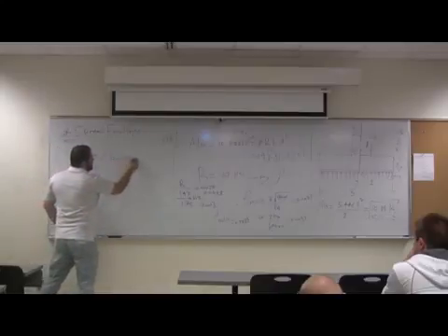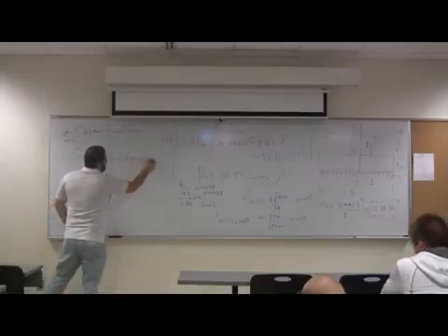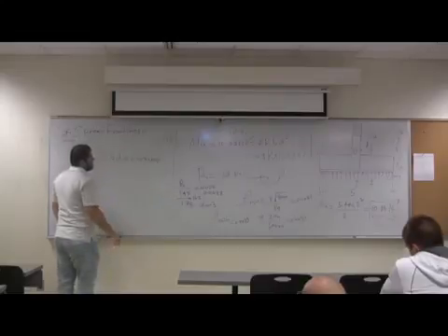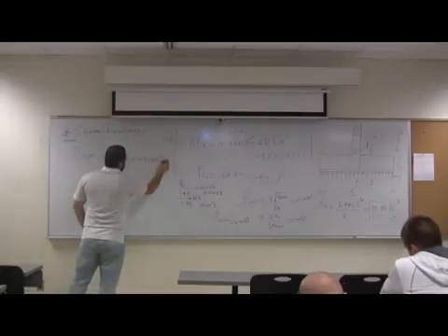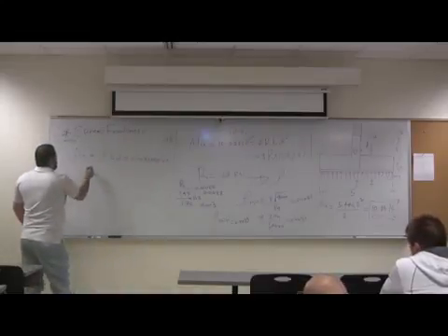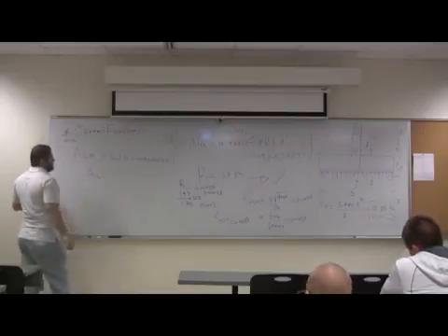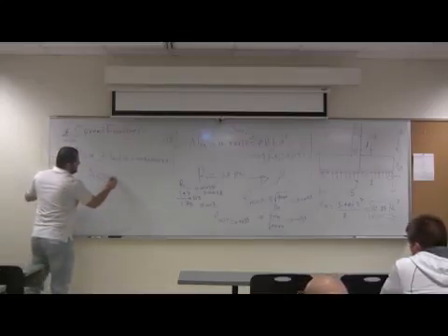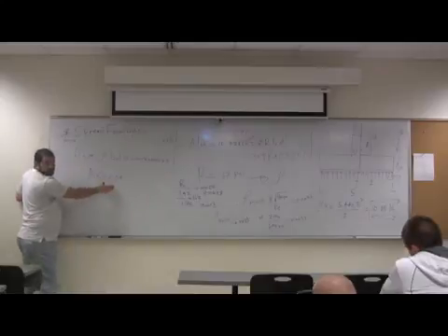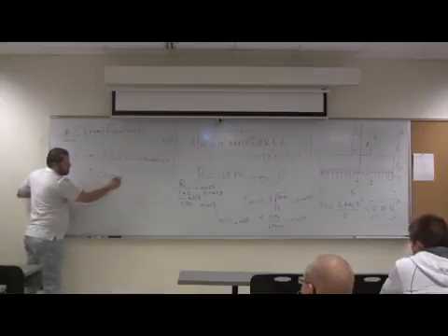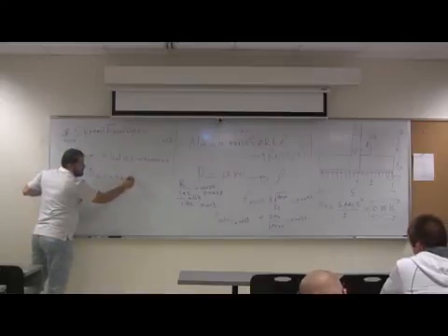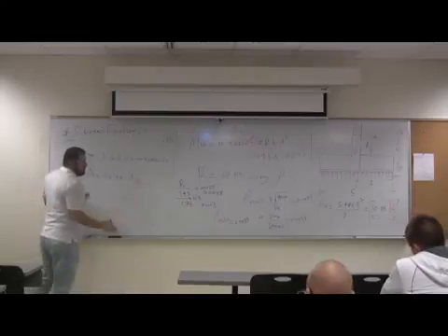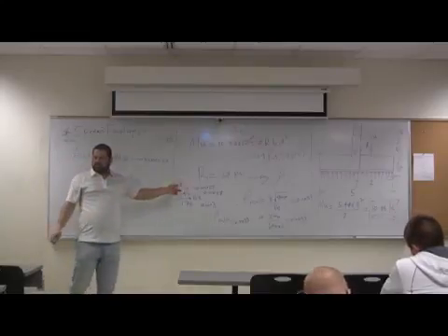So this is 0.0033 times 12 times how much? 8.5. Your AS will be 0.34. Wait a minute, what's that number now? Inch square per foot. For each strip, each 1 foot, that's how much steel it needs.